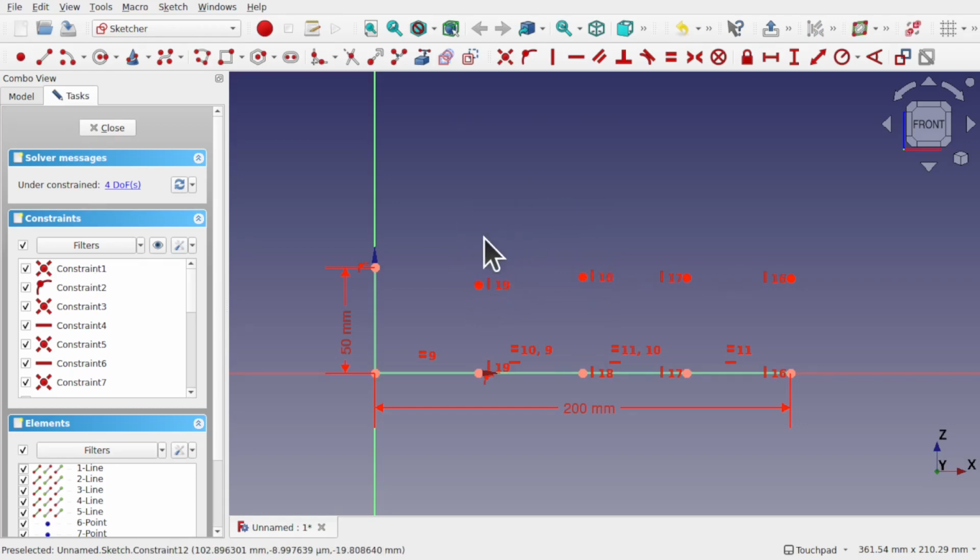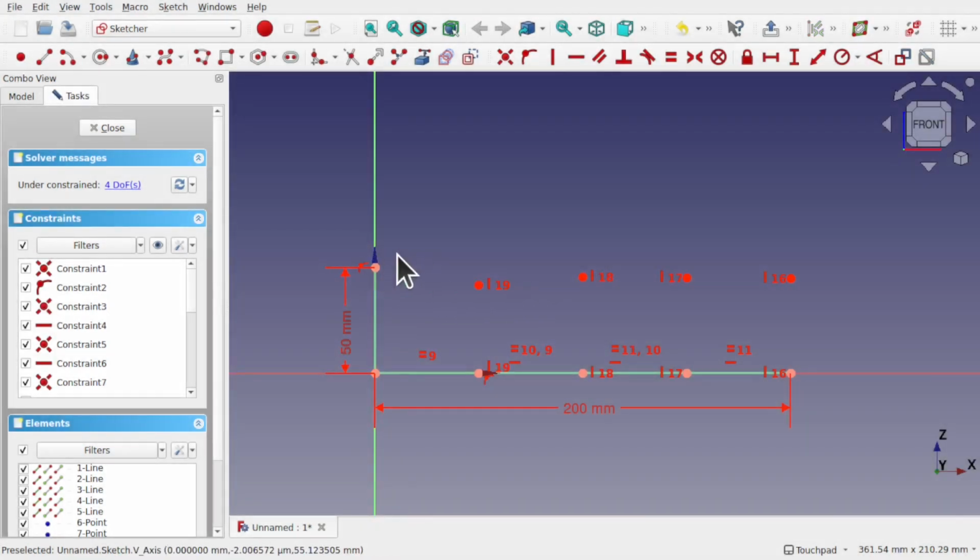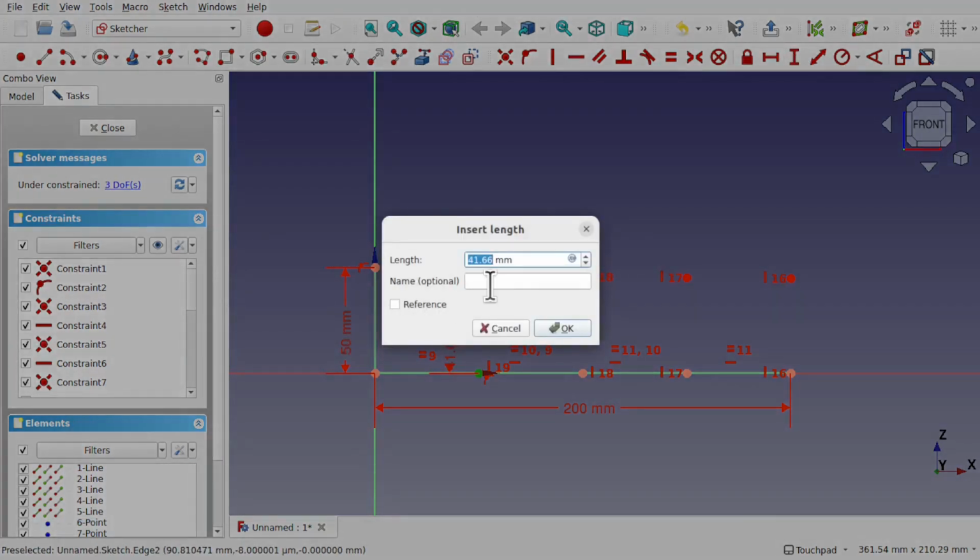So now let's name these constraints. This one here, I'm going to call this point 0. So this is the starting point of our curve. A B-spline will connect all these up. So this point 0, this one here, that sets some height between here and here, and you can see why we need this polyline now. Height, and this one's going to be point 1.